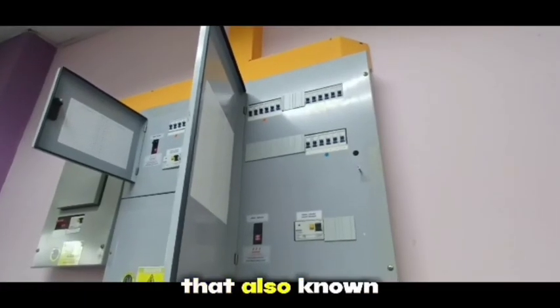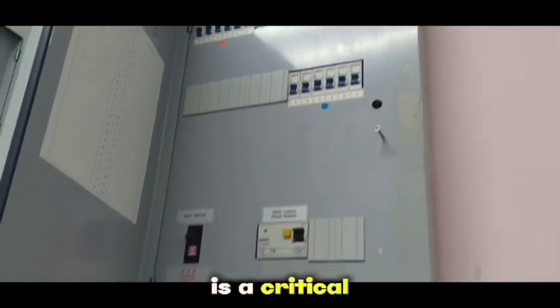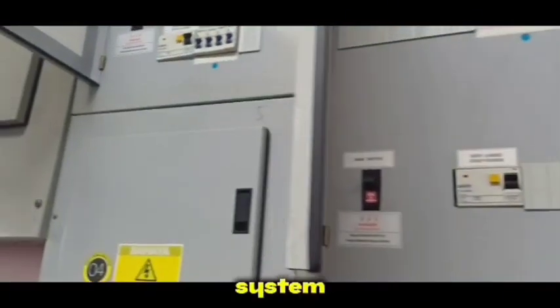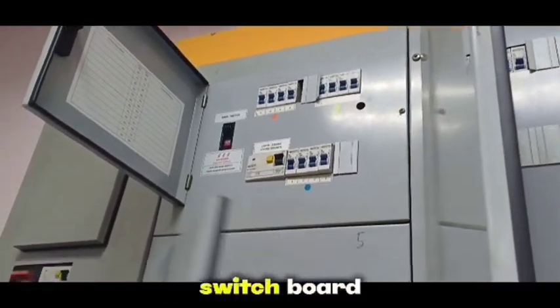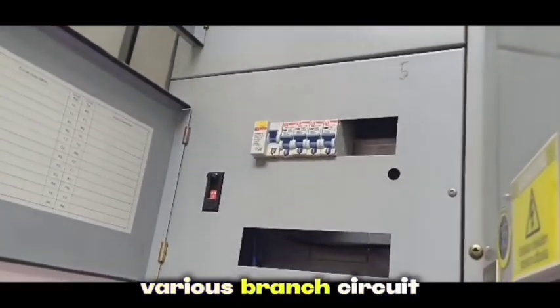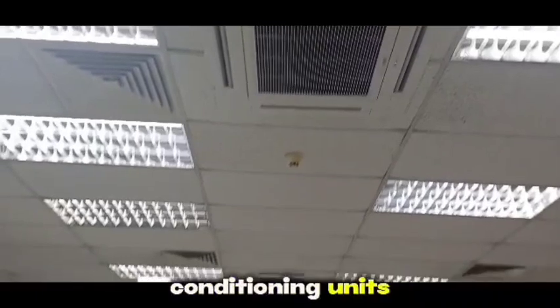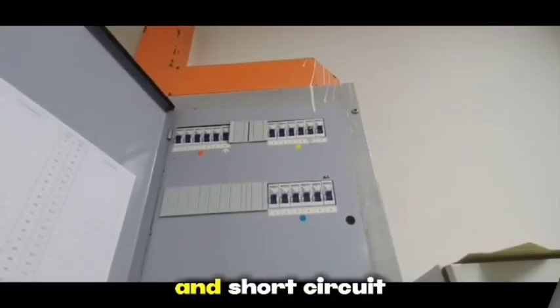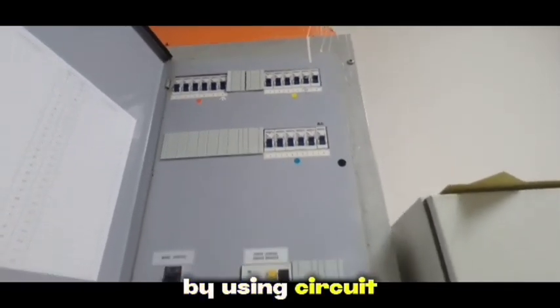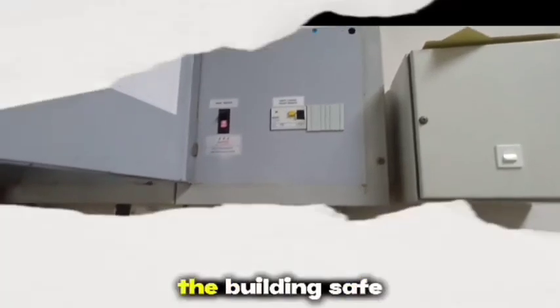A distribution board, also known as a breaker panel or electrical panel, is a critical component in an electrical system. A distribution panel receives electrical power from the main switchboard and distributes it to various branch circuits such as lighting, sockets, and air conditioning units. It also provides protection against overloads and short circuits by using circuit breakers that trip and stop the flow of electricity to help keep the building safe.